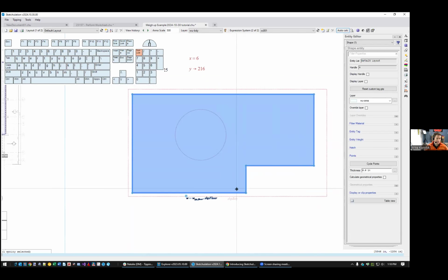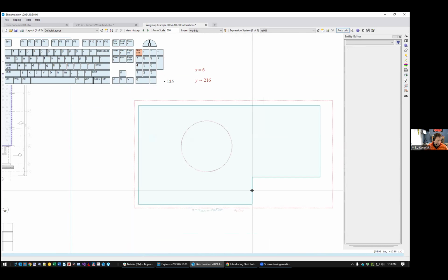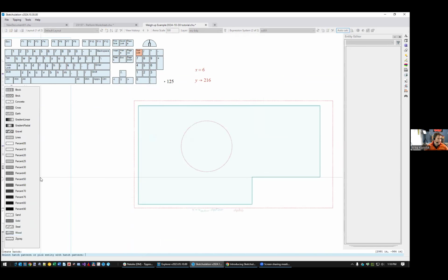And I'm going to use this shape and this shape to make a floor opening with a gigantic hole. So I use the command HB, hatch boundary, right here. Click on that. I tell it what type of hatch to be. I'll make that a solid.